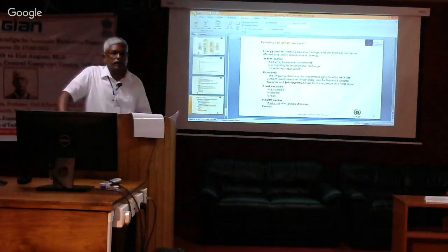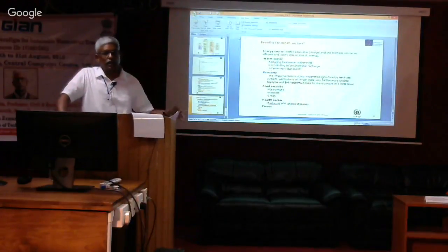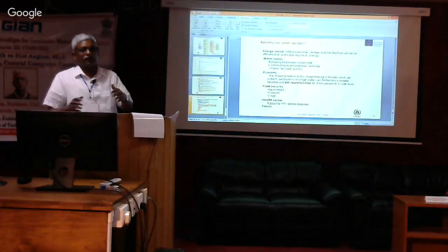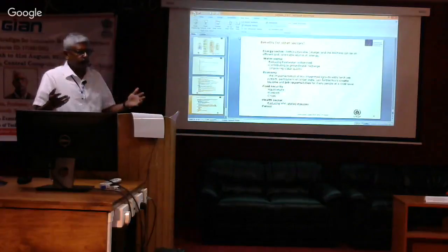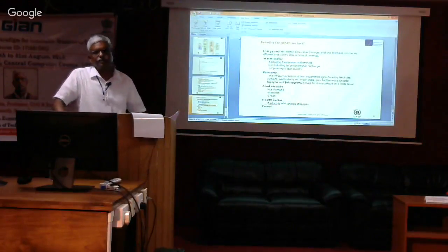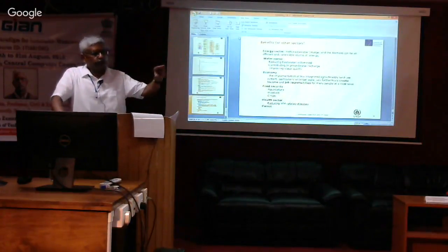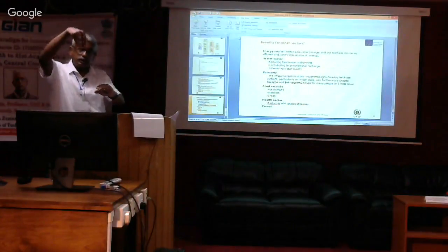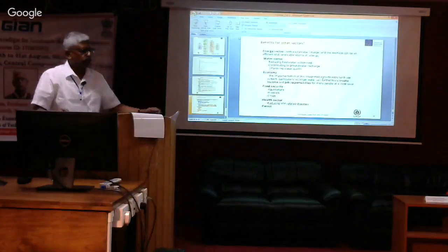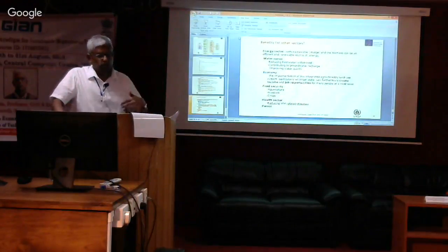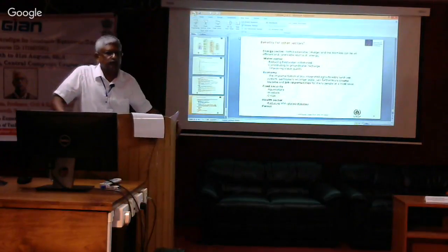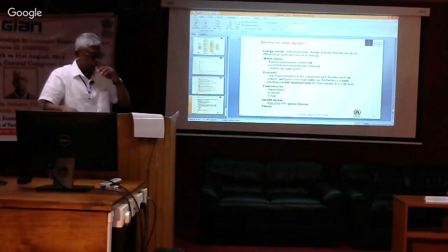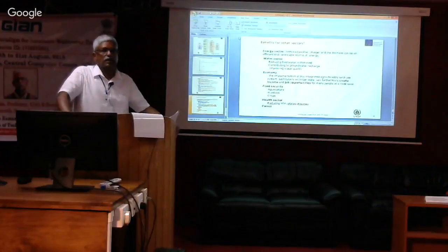We now have very good technologies where this water that comes out of the septic tank, if you aerate, if you have an anoxic atmosphere, then you have a biomat. That means the soil has a biomat. So as this water percolates, the biomass is able to absorb or transform the organics much more. And so at the end of that process, the water that gets into the groundwater is much, much better.